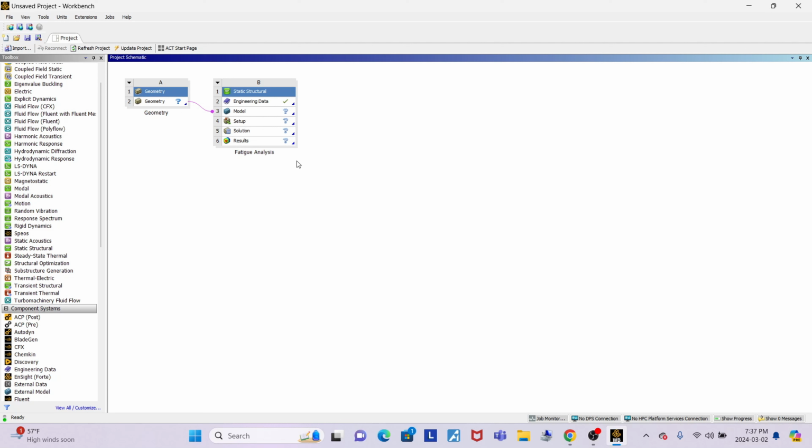So I hope in this third tutorial you will be able to know the analysis system, the component system, and how the component system and analysis system can be shifted to the project schematic, and how to transfer the geometry, a component geometry or other component system to an analysis system.